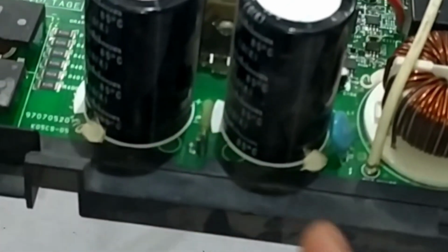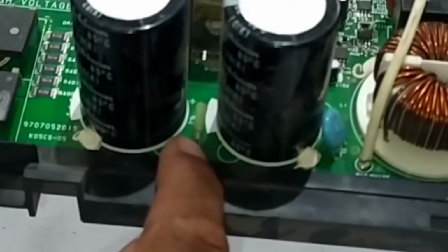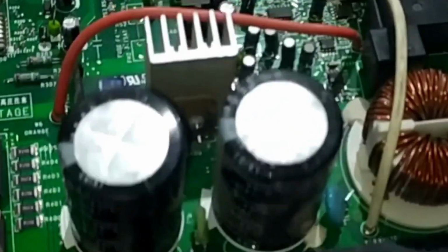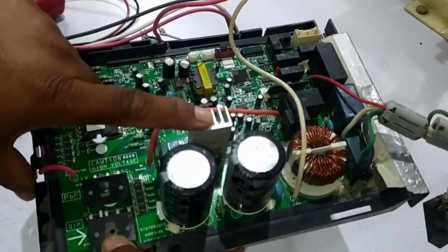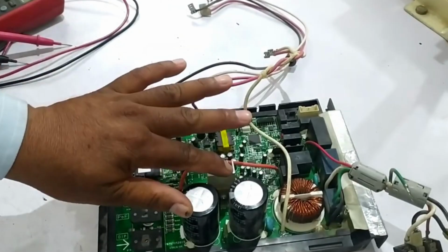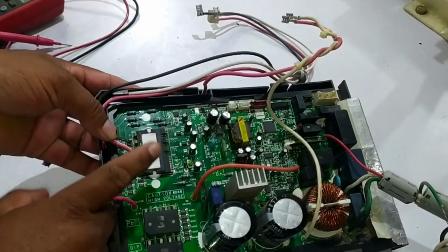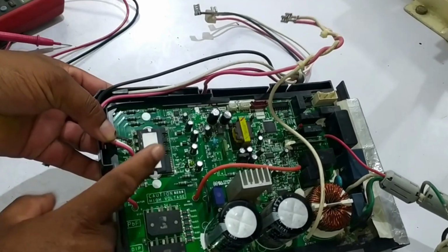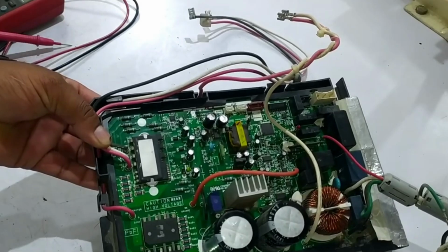Next, you need to check the discharge resistor, which should have 5 volts. If it is receiving 5 volts, then it is functioning correctly. After that, inspect the recovery diode and test the IGBT, insulated gate bipolar transistor. Once these components have been checked, move on to testing the IPM, Intelligent Power Module, as it can also cause the unit to stop working after running for some time. If a fault like this occurs, the compressor also stops working.